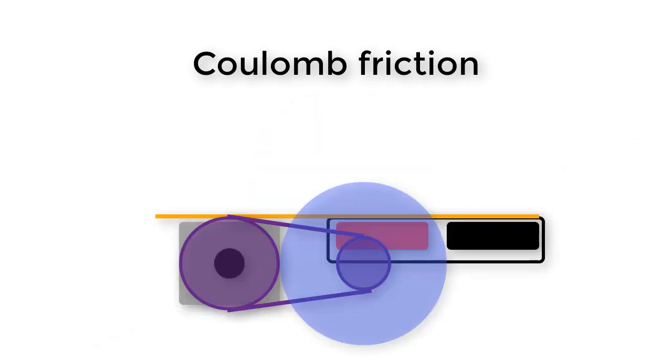In particular, there is dynamic Coulomb friction also. In our system, parts rub against each other in the bearings, between the wheels and the axle, inside the motor, and inside the transmission. All of these sources will contribute to cause our system to lose energy through Coulomb friction. Coulomb friction is independent of the velocity of the wheels.